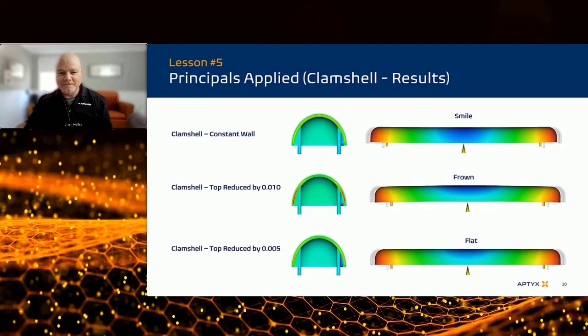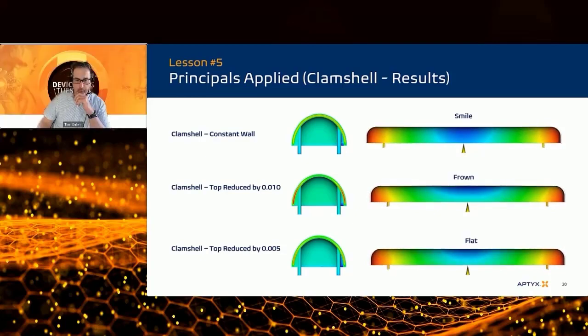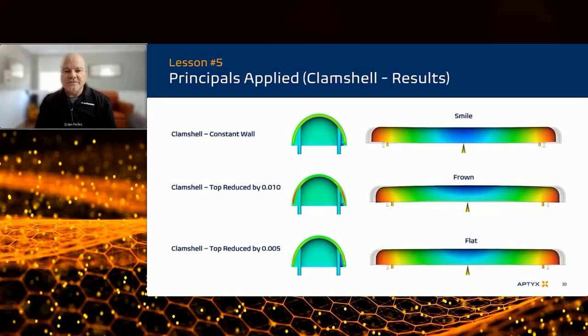Are there concerns about structural integrity if you don't have uniform walls? It's a great question as well. So yeah, you could be taking out material where the part's going to get hit. And when you do these things, as far as thin up, this is a very slight change in thickness. You do want to validate with more simulation and do that virtual drop test to validate that these as-manufactured properties are going to hold up to the virtual and the real world when it comes to product testing or product use.